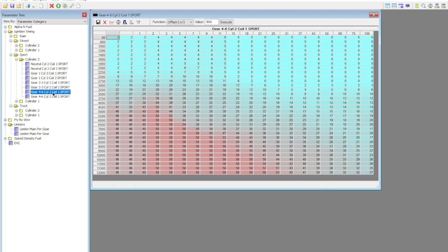You can start increasing timing gradually, 1 degree at a time, see the improvements on the dyno, and if it stops making an improvement with an incremental degree, take the degree out. Don't leave it in there. That's just going to add extra stress on your rods, your piston, and reduce your safety margin against detonation. So any tuner should know this, should be very reasonable.